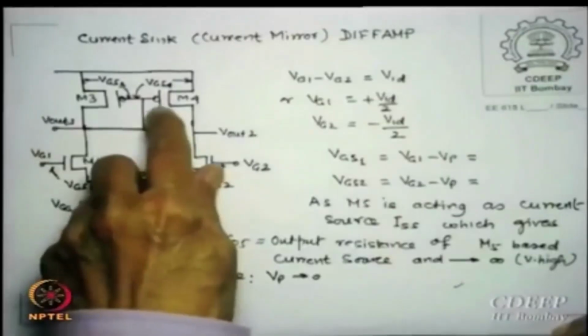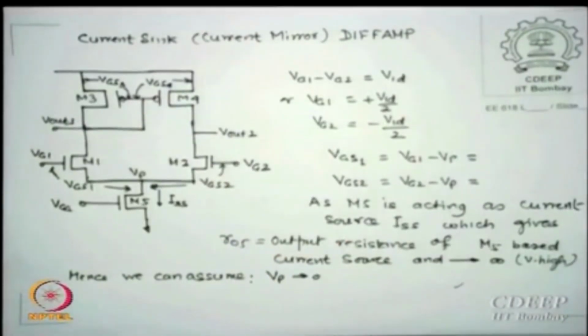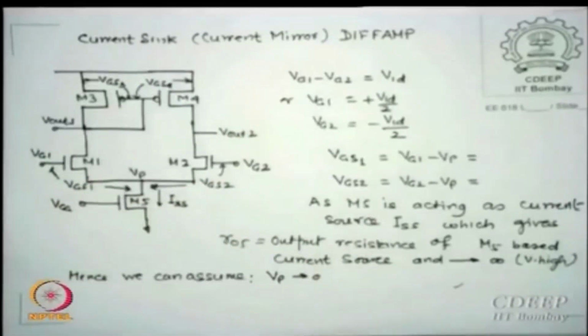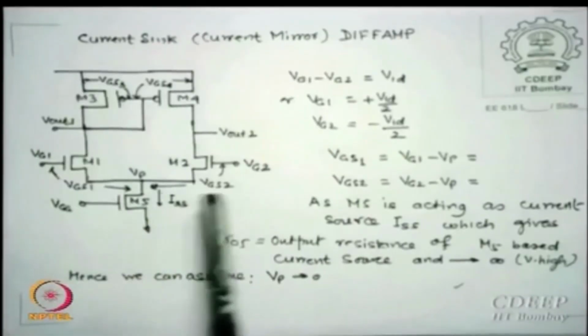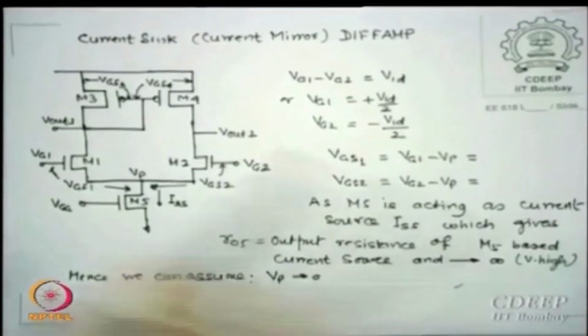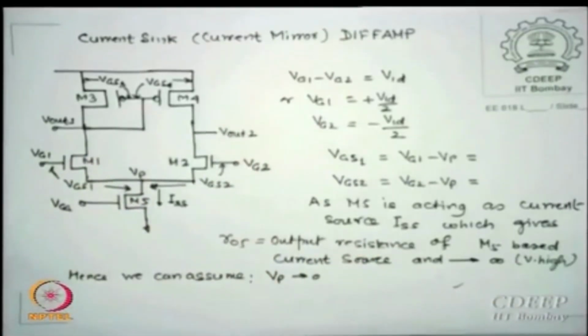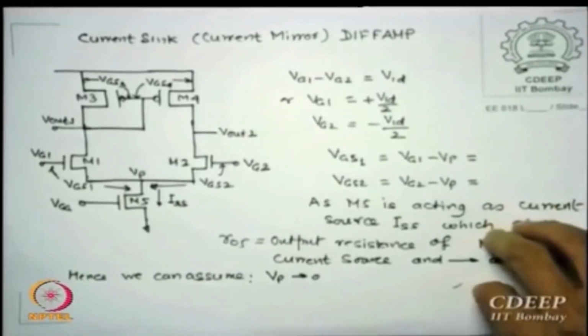What we said last time is that since Vout1 is an AC output, for M4 it is acting like an input, because it is connected. So there is an input signal for M4 and there is an input signal for M2, and since both have the same output resistance, at the node both transistors give RO in parallel. Therefore ROP parallel RON is always the output resistance, independent of whether you drive from here or from here, and if you superimpose them, the output Vout can be obtained.